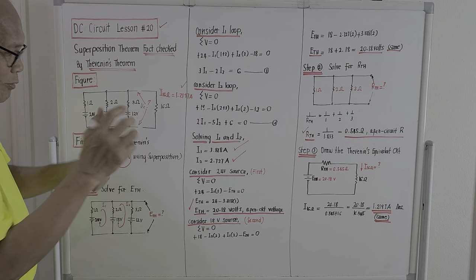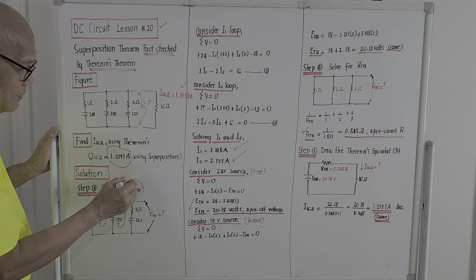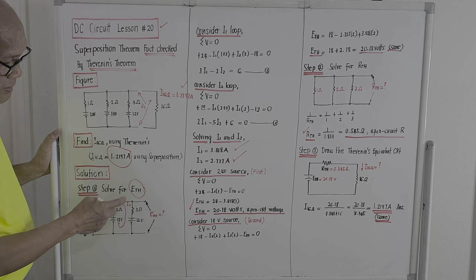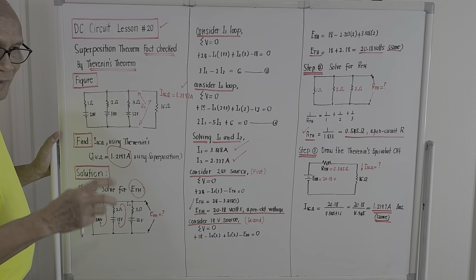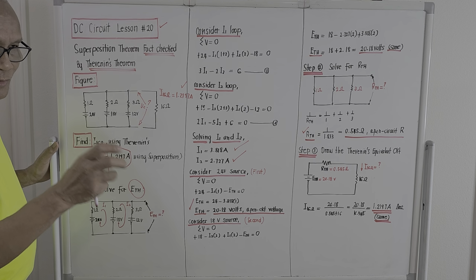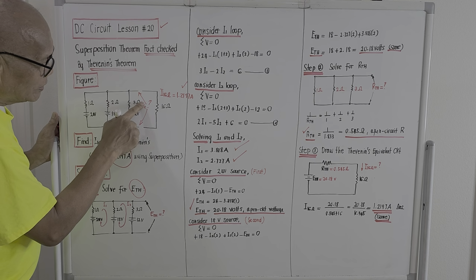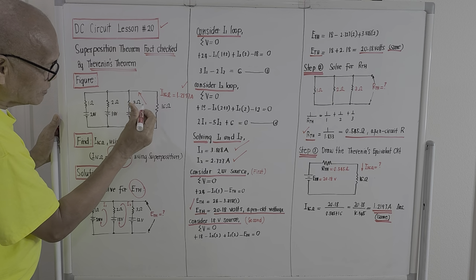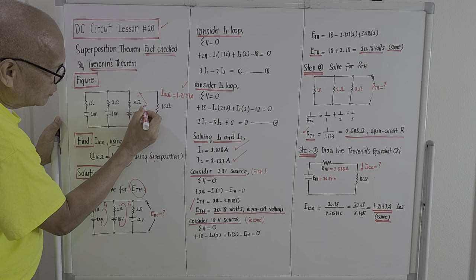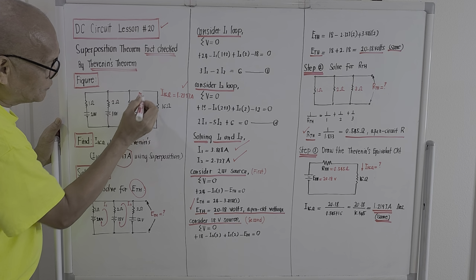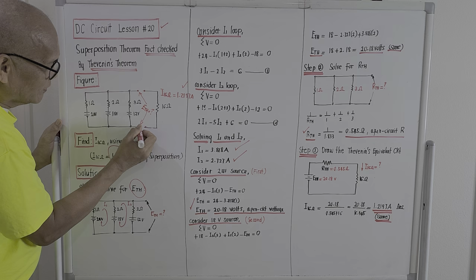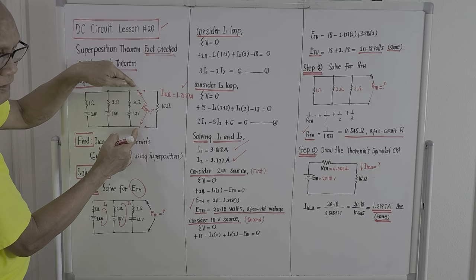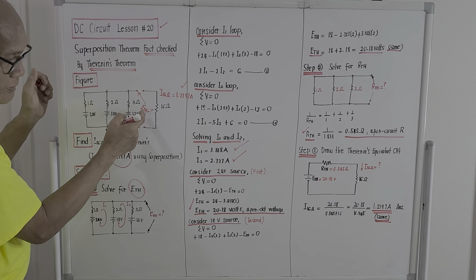In Thevenin's theorem, we call that one ETH. ETH is capital letter E, and the subscript TH refers to Thevenin's. ETH is referred to as the so-called open circuit voltage. So actually, what we could measure here is the voltage designation ETH, after the disconnection, because we will disconnect the load first. This is an open terminal where we get our voltmeter reading, ETH.